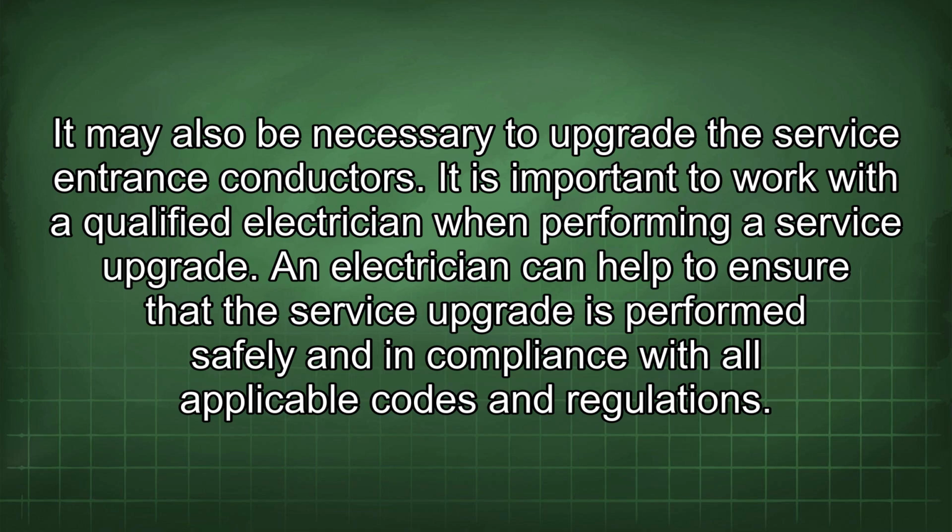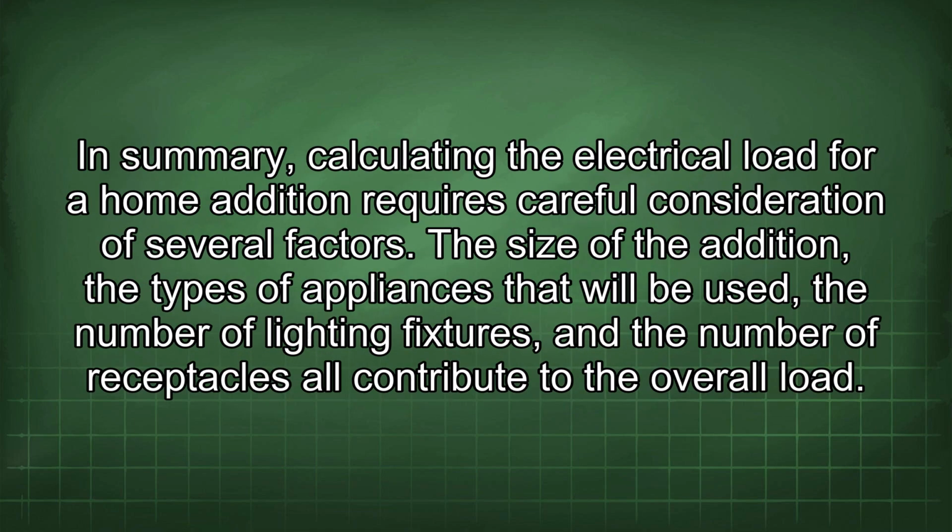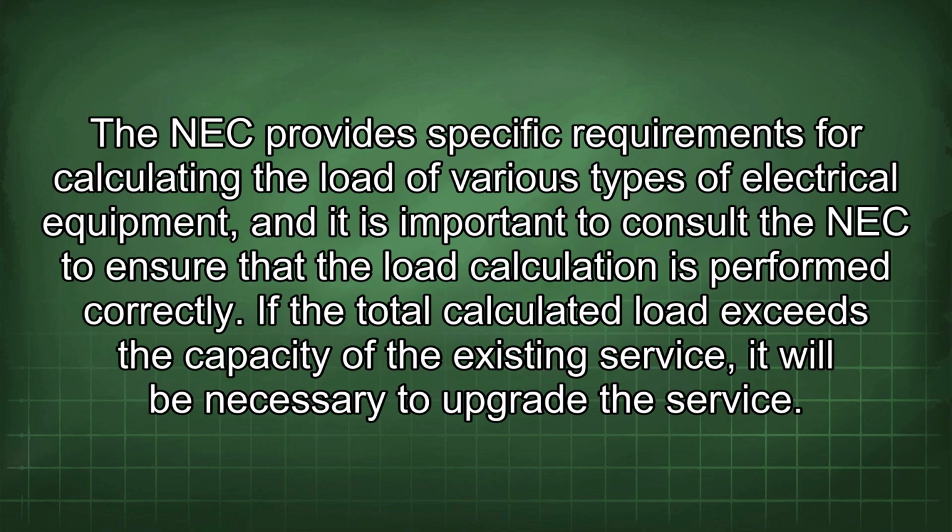In summary, calculating the electrical load for a home addition requires careful consideration of several factors. The size of the addition, the types of appliances that will be used, the number of lighting fixtures, and the number of receptacles all contribute to the overall load. The NEC provides specific requirements for calculating the load of various types of electrical equipment, and it is important to consult the NEC to ensure that the load calculation is performed correctly. If the total calculated load exceeds the capacity of the existing service, it will be necessary to upgrade the service.